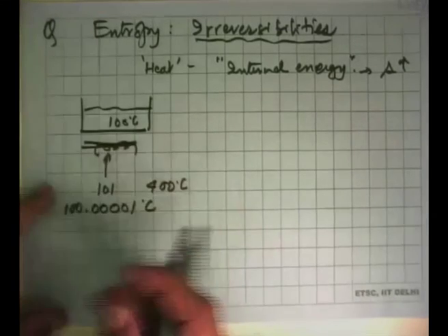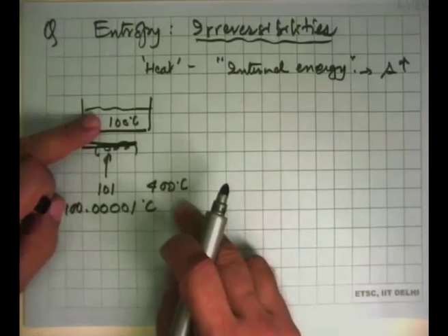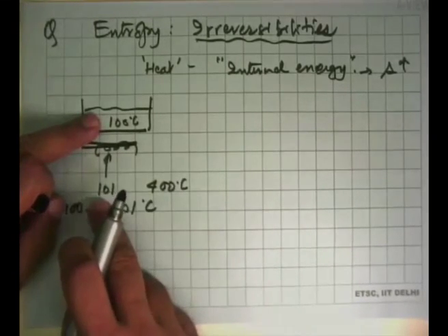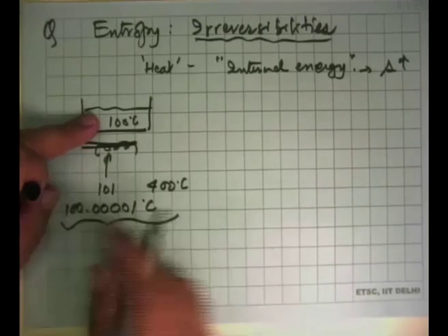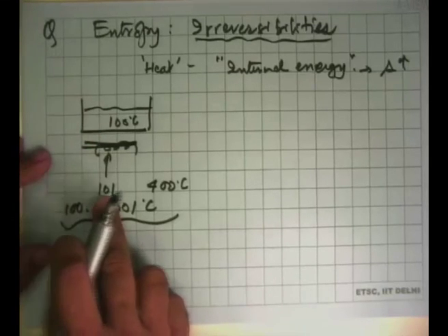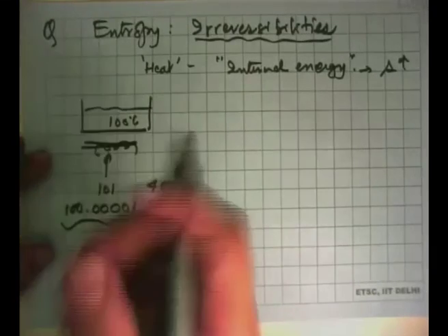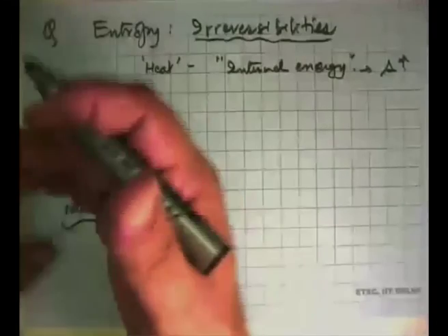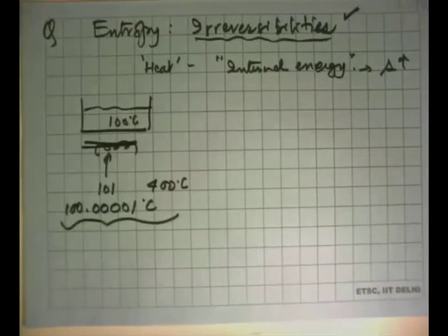Now you can see that when you do this to heat it, there is a big irreversibility associated with this. With this, the irreversibility is less. With this, the irreversibility is even less. But practically, we know that if I heat it up by 1 degree difference, it will take me a whole day to heat this up. And that's no fun. So, to increase the rate at which processes happen in the practical world, we do go for finite rates of change, and that brings with it irreversibilities.